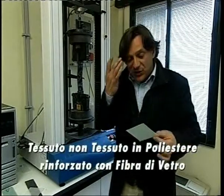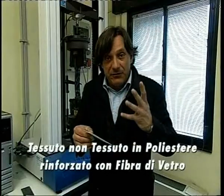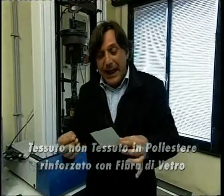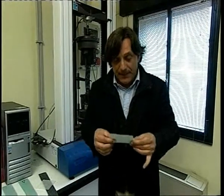Latest generation reinforcement structures are even reinforced inside by filaments of fiberglass. This is because even if polyester has remarkable properties of mechanical strength, it cannot ensure the dimensional stability offered by vitreous coating, precisely because vitreous coating is an inorganic substance. Today's technology allows us to combine the excellent qualities of dimensional stability offered by vitreous coating with the excellent mechanical strength of polyester.